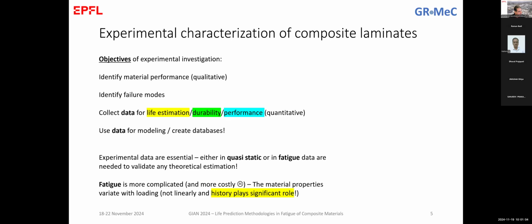You will see also later on Thursday probably, when we talk about fracture mechanics, for years, even in the standard of mode 1 testing, mode 1 is an opening. You have a specimen and you try to open it and measure the mode 1 performance. And due to the lack of methods for online measuring devices at the time, the standard suggested to interrupt the test, the fatigue test, and open quasi-statically the specimen, take the measurement of the crack, and then continue the testing. And it was nice, it was okay for very brittle materials, for aerospace. But when we switched to materials for civil engineering, for example, that are softer and more ductile, we've seen that there was a great effect of this interruption to the fatigue life of the fatigue and fracture performance of the joint.